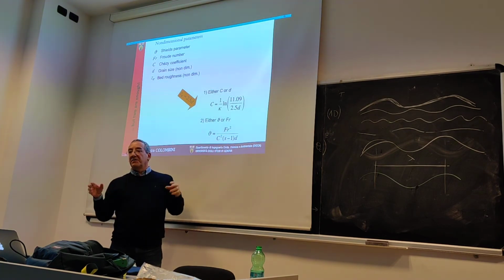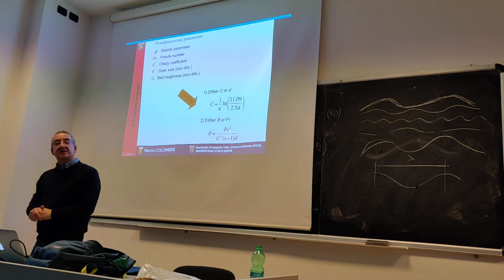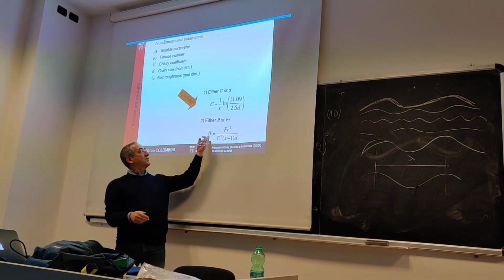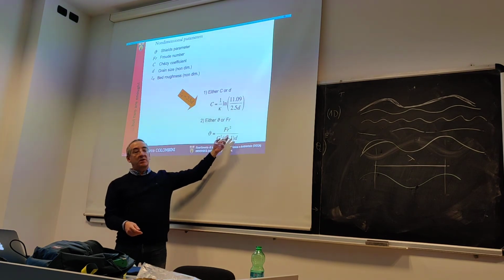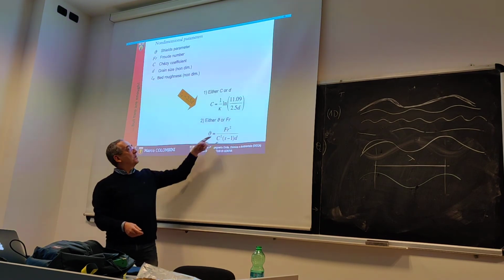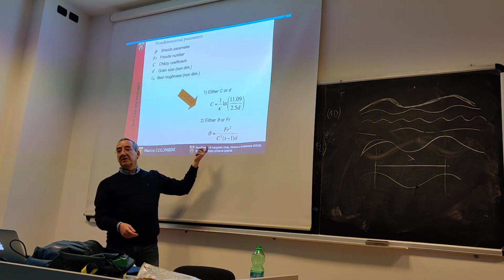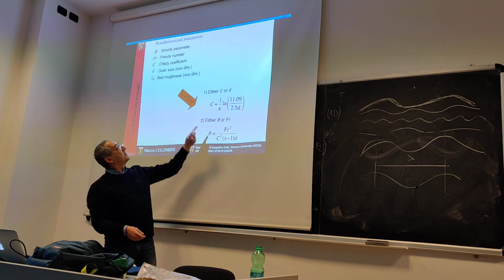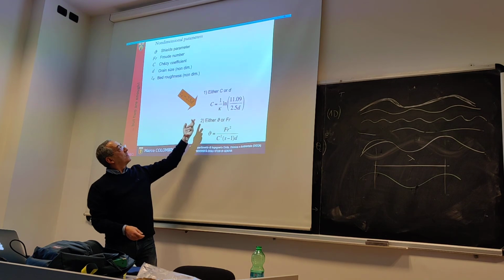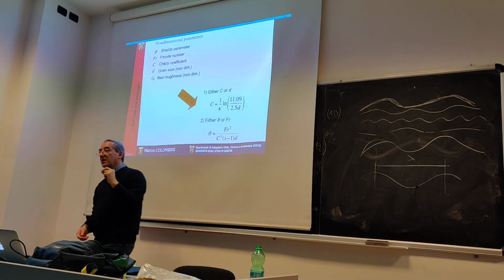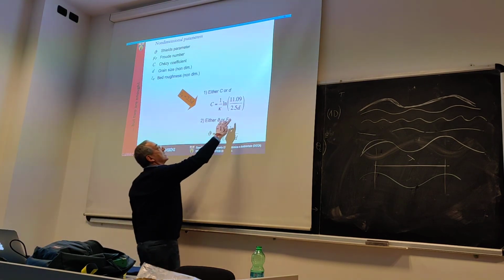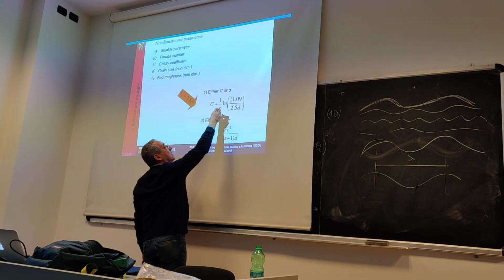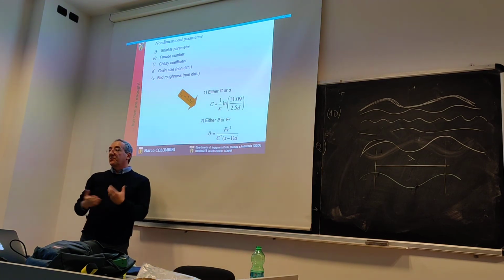So you can have your parameter space with a Shields flavor, as I call it, or a Froude flavor, because the two are related by this relationship. And the same is true for the Chezy non-dimensional coefficient and the non-dimensional roughness. You can use either C or D to measure the roughness.